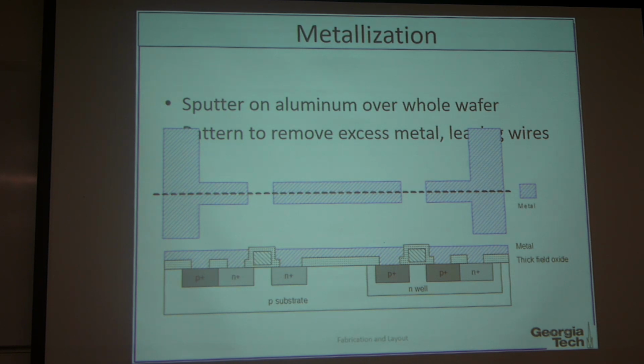I think now I understand what your question is. So why is there P plus and N plus together, why not just N plus altogether? This is the body substrate bias, which is a reference value for tuning the VT, threshold voltage. So we need this P plus to be there to properly connect to the body. It's working as a body bias. I'll talk about more detail after this class.